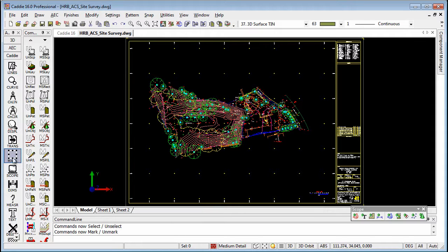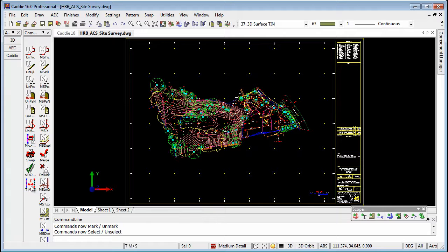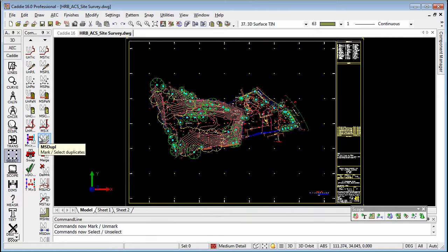So how do we make use of these for selection? Well, coming into the mark tools, we'll see down at the bottom we have a toggle between mark and scope, and that will toggle it to select, so all the tools now relate to selection rather than mark. Another alternative is to press the tab key at the time you select the select or mark tools, so it just toggles between the two.